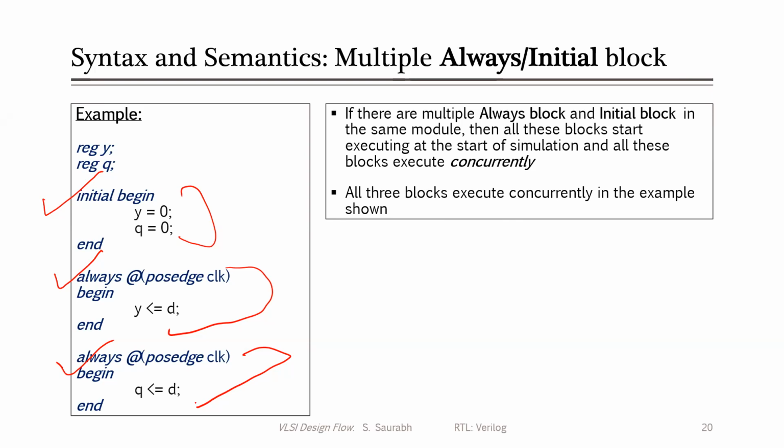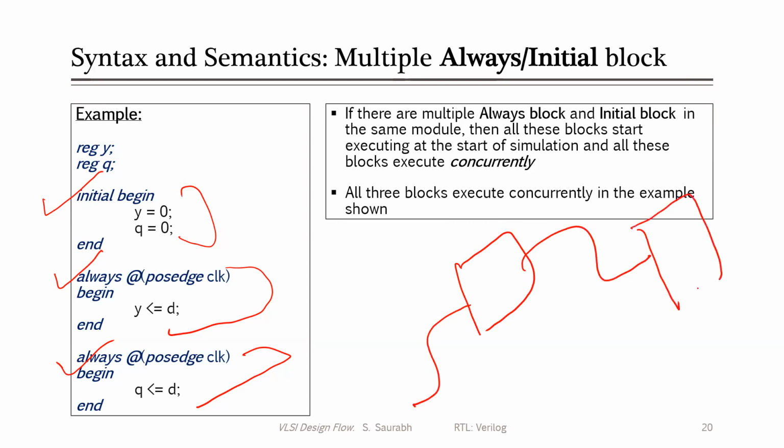If you want to actually control it, then you should say that this is my block which will be executed first, then the output of this goes into the next one, and so on. If there is an order, you have to specify it in a particular way, as a sequential block of code that will be executed in that particular manner. So there is a way in which a sequential operation can be specified in a hardware description language.